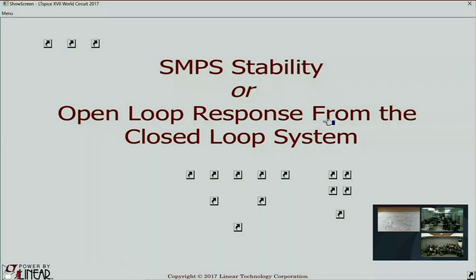Because if you have 180 degrees phase shift, you have positive feedback, which means ringing exponentially increases with time instead of decreases with time. But if you get this positive feedback only when the gain drops to below 0 dB, you're attenuating that, so you're good. That's the main thing you learn in stability analysis. All the rest is just a detail, really. That's the main idea. So let's rethink this.